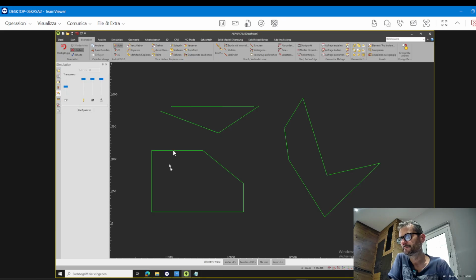I take delete, and I go near to my shape, to my geometries, and you can see the selection. This kind of line is the selection. And you can see in this case I have this selection, and this. So there are 3 pieces: 1, 2, and 3.